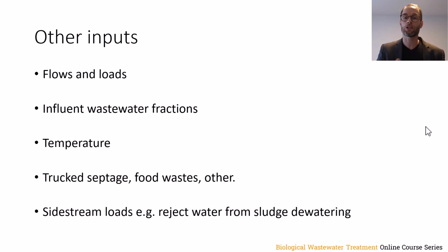In addition, side stream loads. At some plants, they will operate their sludge dewatering 24 hours a day and 7 days a week. And so if we're thinking about the reject water from anaerobically digested sludge that's being dewatered, that load being returned into the activated sludge process under those conditions can be treated as a constant load and simulated even under steady state conditions. However, many plants don't operate 24/7.